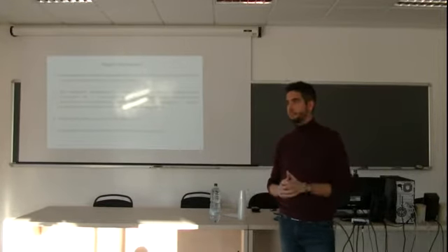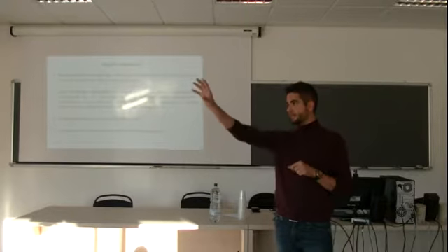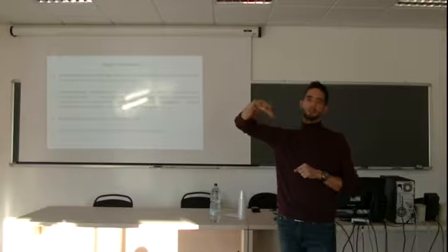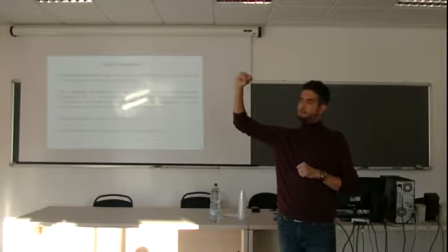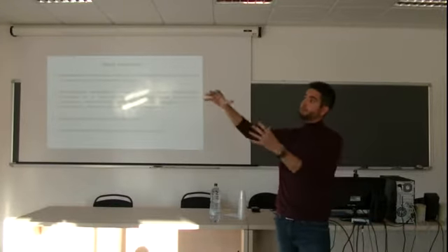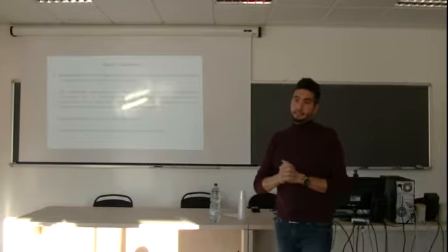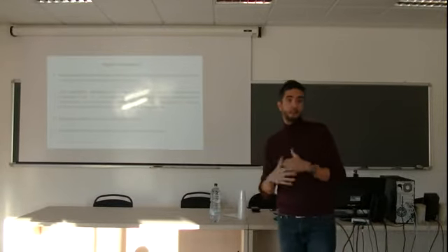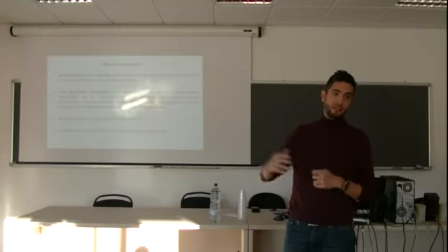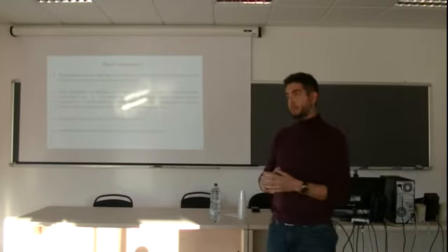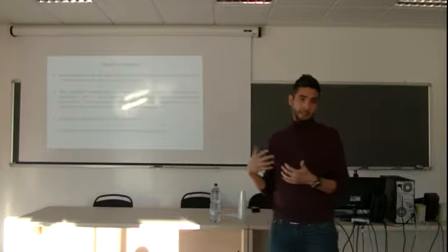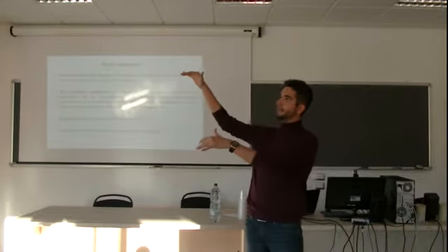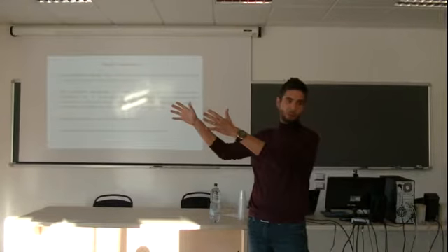For example, imagine we have just one window, and I want heating and cooling of this room. The bigger the window, the better for solar radiation going inside, but the worse for heat losses. In summer, it's the other way around. The bigger it is, the more gains from the outside. So there will be an optimum size and shape of the window.